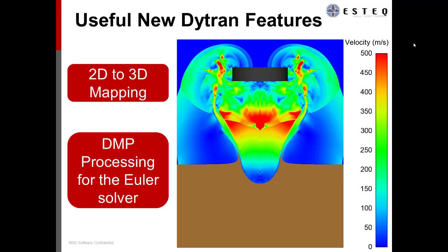So typically you would want to try and perform the mine blast analysis, or at least perform an analysis of the initial stages of the mine blast, using a two-dimensional mesh, because you are able to mesh with a lot finer or smaller elements, and that allows you to capture responses that you wouldn't be able to in 3 dimensions. So this image that I've got shown here gives you an idea of the type of resolution that you can get if you do use a 2-dimensional approach.